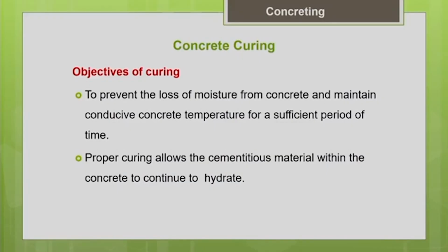So, that is why we need curing. What is the main purpose of curing? It is to prevent the loss of water from within the concrete to the outside environment. The main purpose of curing is to prevent the loss of water, so that the water is available for hydration, and to supplement the water lost. Whatever the concrete has lost to the environment, we have to supplement by curing. That is why we do curing. Curing is nothing but supplying water to concrete.